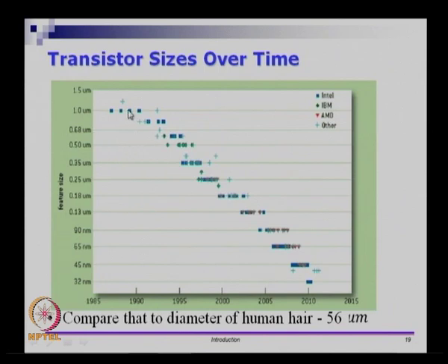So what you see is for every so-called generation, a generation in an integrated circuit is usually about 2 years, for every generation or so it went down by one technology node. One technology node means, in this example there is something at 1 micron, and if you go to 0.5 micron it is probably already 2 technology nodes. So 0.5 to 0.35 and 0.25 and so on, these were the different sizes at which chips were made. Each transistor or each logic element was 0.25 micron in size, and it had millions and billions of these things inside a chip.